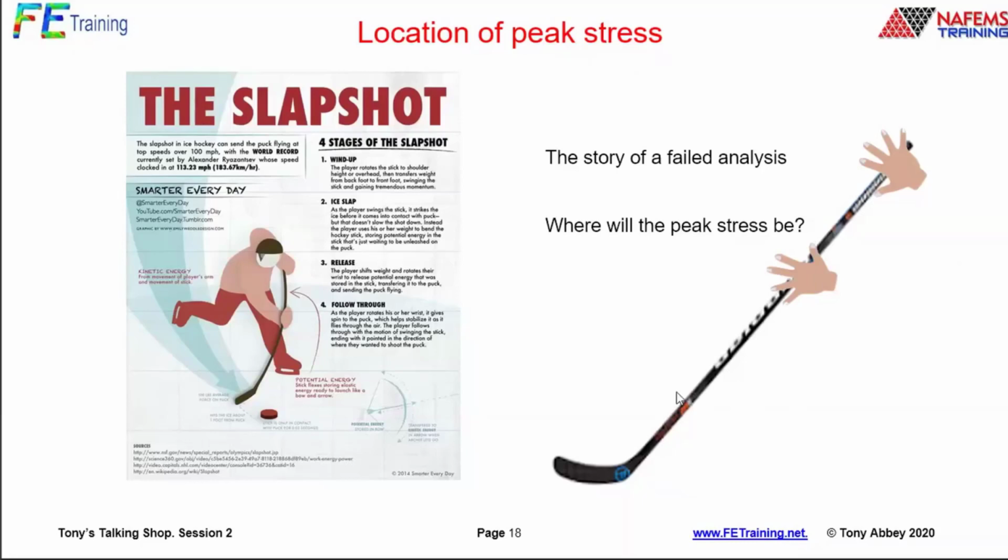So I said, well, how come they got peak stresses there? So he went and looked at the model and he said, they're using a program where they've got a transition between hex mesh down in here and tet mesh down in here, and in that transition zone, the element shapes are so horrible that it's actually creating spurious peak stress concentrations there. I said, well, surely you're not going to accept that. And he said, well, no, but I'm being overridden by the managing director because he says, well, that's where it happened on test. This is where we see it in the analysis, and that was it.